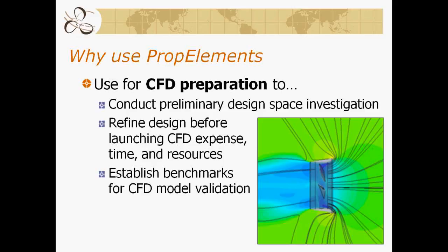A very valuable purpose for PropElements that we're seeing more and more is its use as a preparatory step for CFD. PropElements can conduct a variety of preliminary design space investigations to get you closer to the answer or refine the design before launching CFD with its corollary expense, time, and resources. But one other important aspect is that the quantitative strength of PropElements allows it to establish benchmarks such as thrusts and torques, or even velocities and volumetric flow rates that you can then use for CFD model validation. If your CFD model is substantially different than the outcomes that you're getting from PropElements,